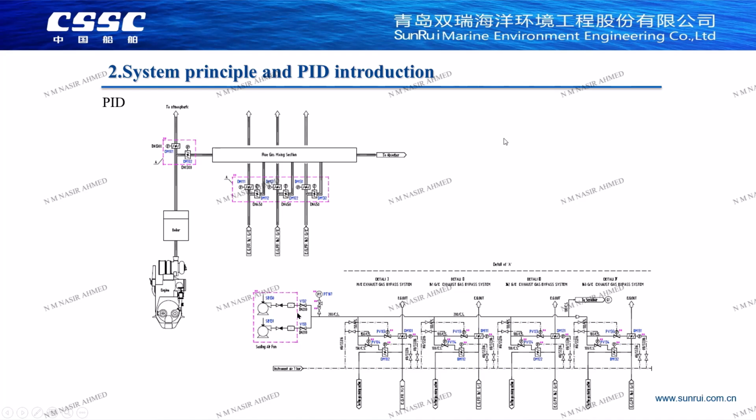In the case of flue gas washing, the inlet flue gas valve will open and the bypass flue gas valve will close. To ensure that the flue gas valve is closed in good condition and no exhaust gas leaks out, we push pressure inside the flue gas valve through the sealing fan. By pressing the air, a tight gas seal is formed and the effect is good.